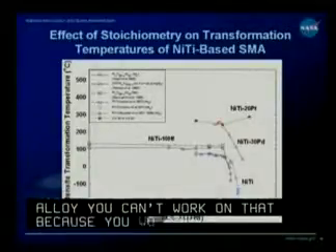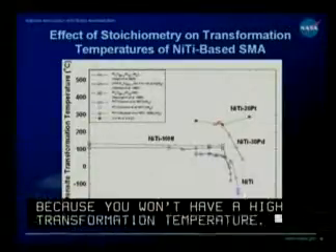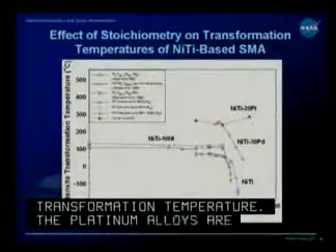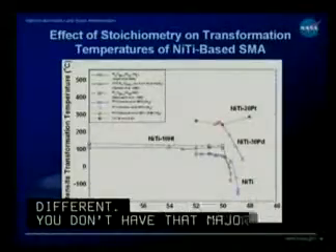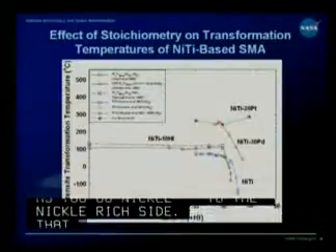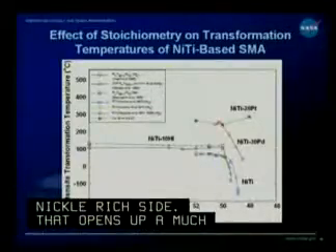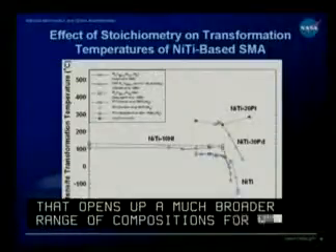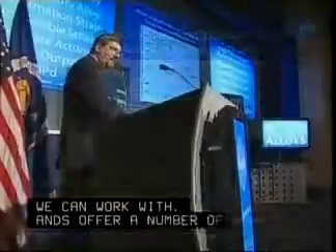The platinum alloys are different. You don't have that major loss in transformation temperature as you go to the nickel rich side. So that opens up a much broader range of compositions for which we can work with and offers a number of very interesting things along the way. If we could have the next slide.